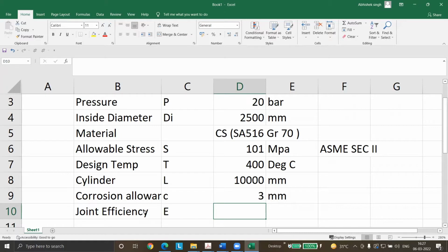So liquid penetrant examination, LPE. You can check how it is done, so it will give you a really great idea of how surface examinations are performed. MPE is for magnetic particle examination. It can be done only on ferrous materials because it depends upon the magnetic property.